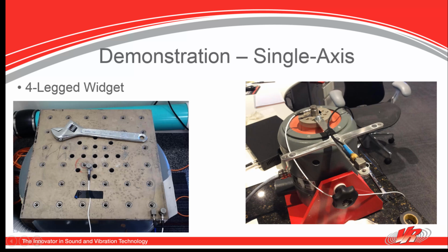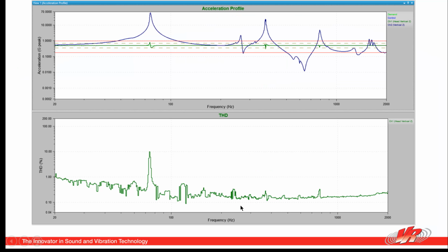And so the feedback that channel 1 is giving back to the drive is that there is this vibration, and so the controller tries to compensate, and you'll find that then there's a little bit of issues controlling through that resonance, but not bad, and the total harmonic distortion is not terrible, but it is a higher value here, so it does indicate something's going on.